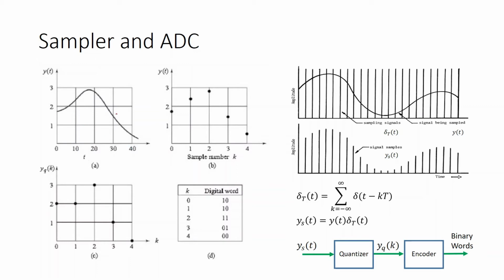So what is the value at 0? This is the exact value you see given by the black dot in figure B, and exactly at 10 this is the exact value. In this way we are sampling the signals. In sampling, how does it happen? We basically multiply a continuous signal with a train of pulses, a train of impulses. The train of impulses is mathematically represented like this. I hope you remember this representation of signals from your signals and systems class. Of course you will tell me that we cannot generate impulses in a practical situation. Sure, these are not impulses, these are unit steps of very small width, very small width pulses.